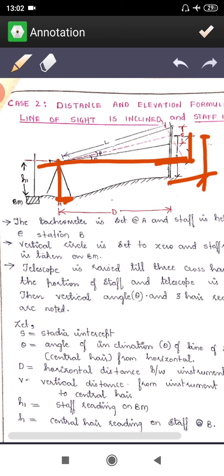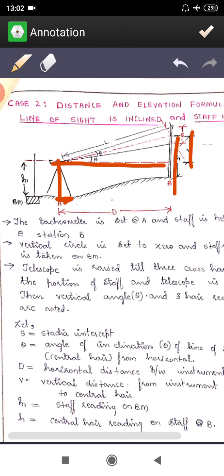You getting this? See here, when you come up to here, then you go to this, and from this to this is your H. So it is going to be 77.750 plus 1.42, then you come here, plus V you are supposed to add, that is V we have got 6.930, then minus H you are supposed to go to the ground, means you come down here.